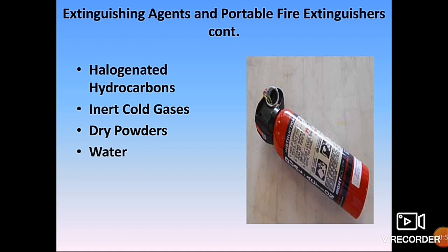Normally CO2 is a gas, but it is easily liquefied by compression and cooling. After liquefaction, CO2 remains in a closed container as both liquid and gas. When CO2 is discharged to the atmosphere, most of the liquid expands to gas. Heat absorbed by the gas during vaporization cools the remaining liquid to as low as minus 110 degrees Fahrenheit, and it becomes a finely divided white solid, dry ice snow.